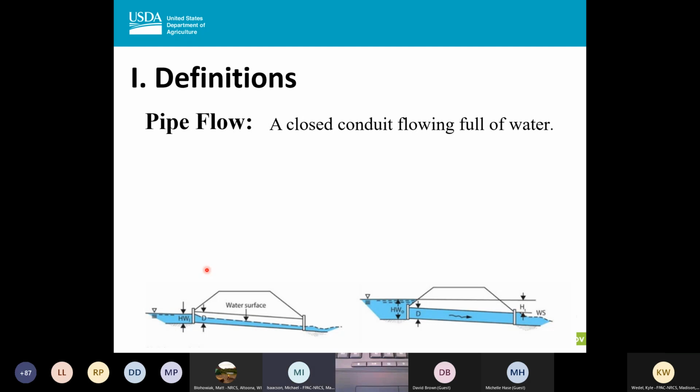Janet actually makes a comment. We need to check both orifice and weirs to see which one controls. And so what she is saying, when you're in that mixed area, is to do both equations. Is that correct, Janet? Yes, Mike, that is correct. That applies mostly on anything non-circular. I think Kyle's rule about the 1/2 diameter is usually accurate, but that hard and fast rule, like he said, does not apply when you come to something non-circular. So it's best just to check. It's easy to check both. It doesn't take much time.